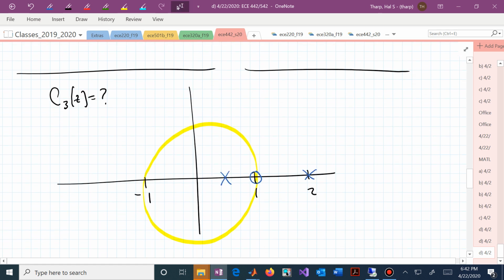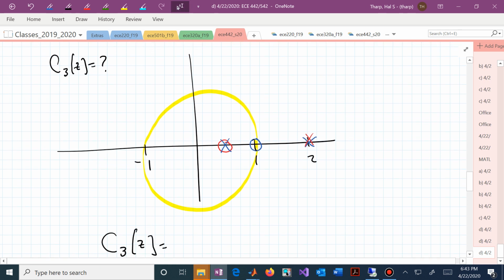Is there another way to stabilize that? And yes, there is. There's all sorts of ways to stabilize this system. This is still the same plant. Now you could actually say, oh, why don't I just put the pole right there at 2 and again cancel that particular 0 or the pole at 1/2.